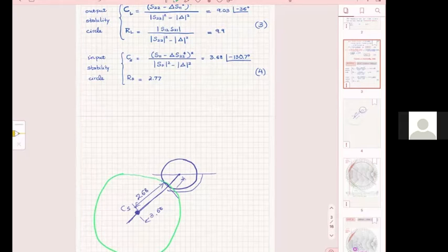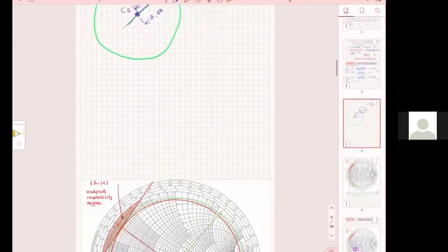And why is it going to look like this? Because the distance between the end of the Smith chart, which is right on this blue line here, which is somewhere here, and the point where the circle intersects the Smith chart is very small, because the radius is 2.77 minus 2.68. So practically, how much do you have? 0.09. So that is this small difference here. And if you are to plot this, it looks like that.